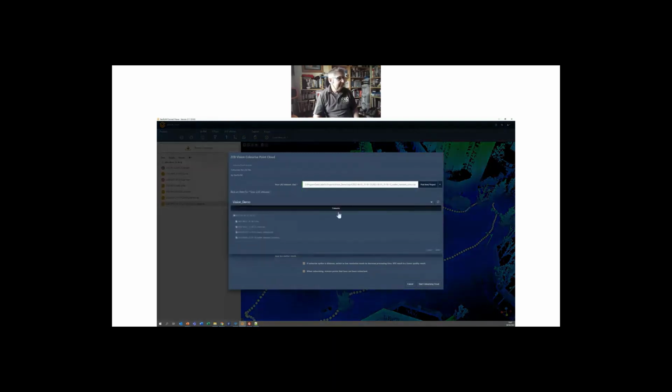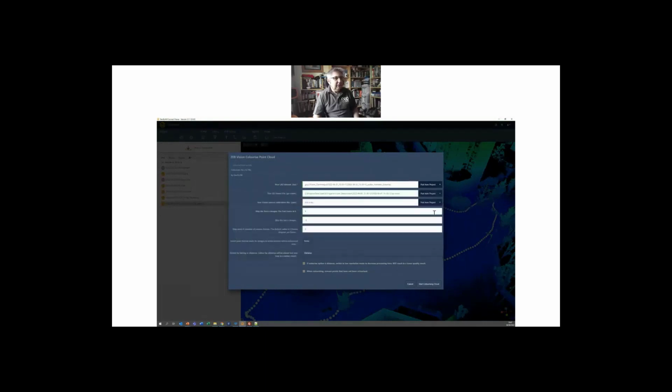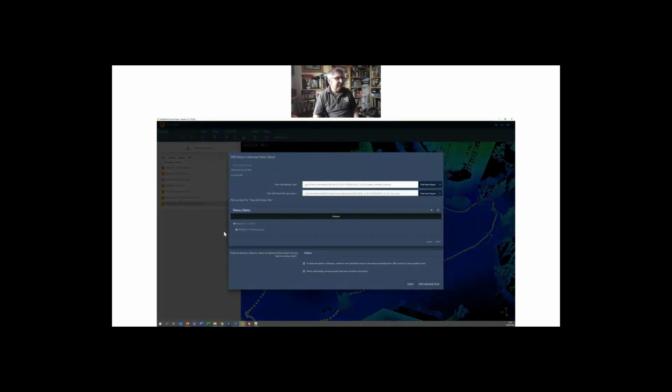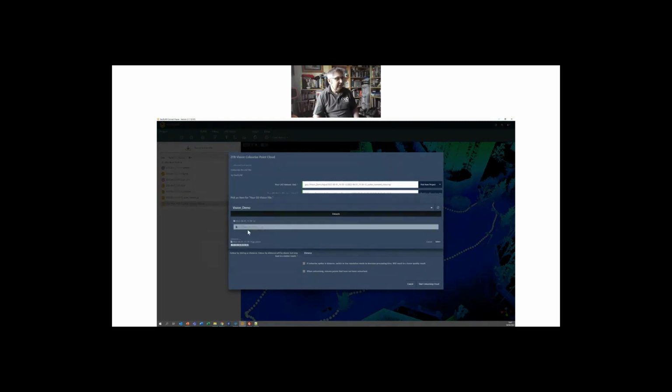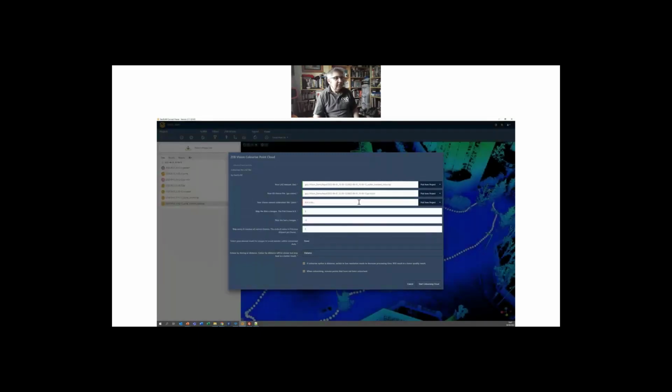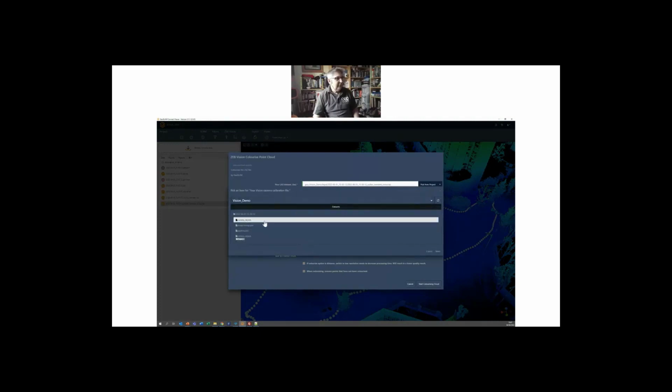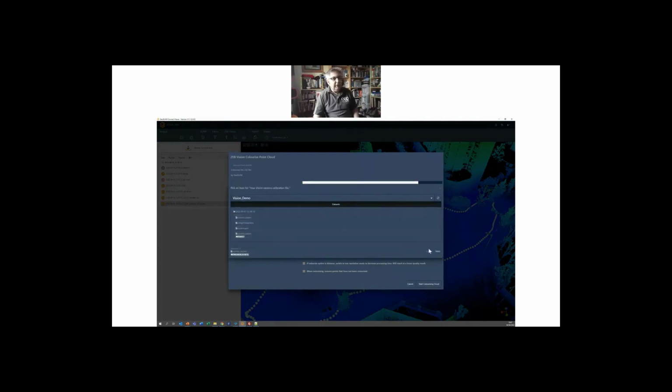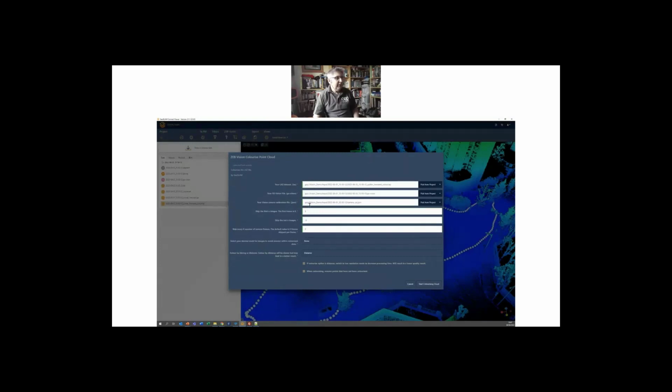We obviously need to tell it, we clearly need to give it the trajectory file, the GS Vision file, so it knows where the images are when they were taken. The calibration file, what we're really using at this point is that if we're going to set a mask, then those mask details are stored within the JSON. So that's why we need to tell it where the project or the camera calibration is, to extract those mask details.